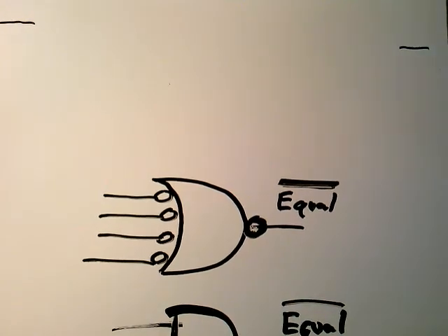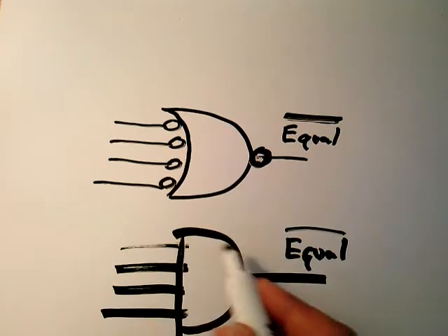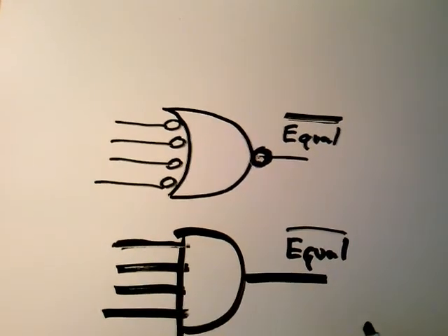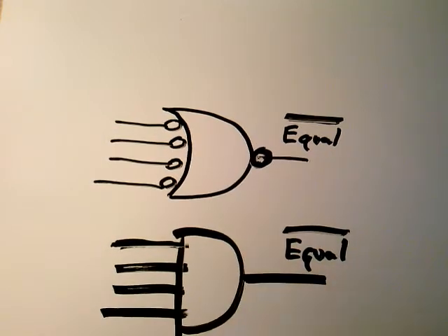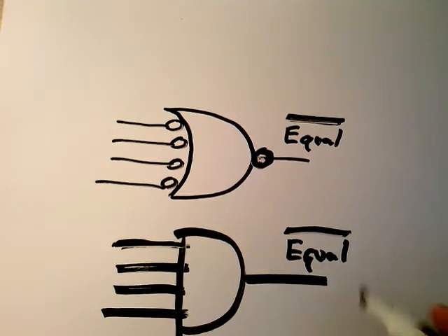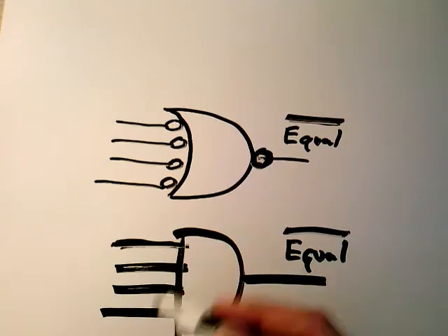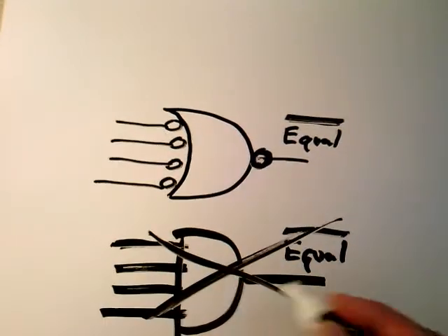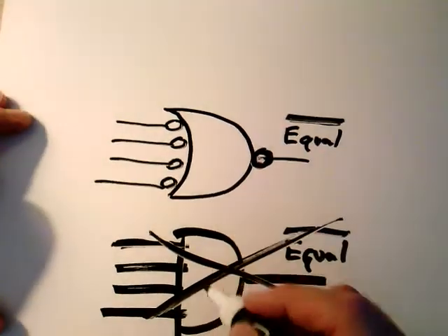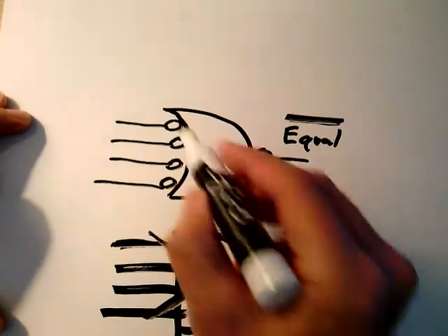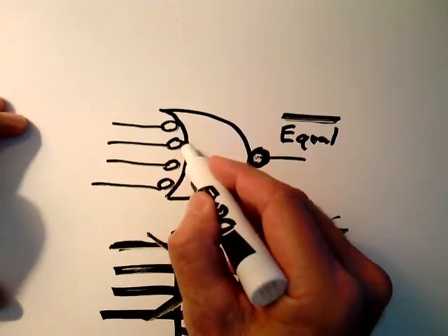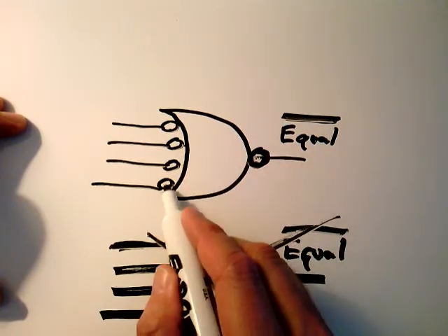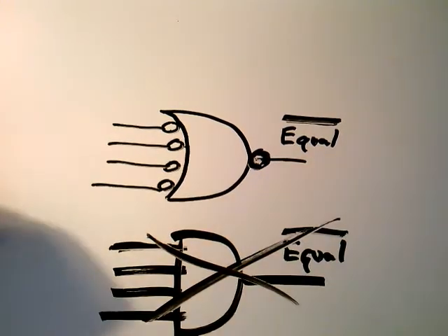But it's convoluted. It's convoluted if the engineer draws it this way professionally, because you have a low active signal, it doesn't match a bubble here. And you're trying to figure out what the heck's going on. Up here, you don't do it that way. Up here, you draw the AND gate like this, like a negative input NOR gate. And this says a low here, or a low here, or a low here, or a low there. Gives you a low there.